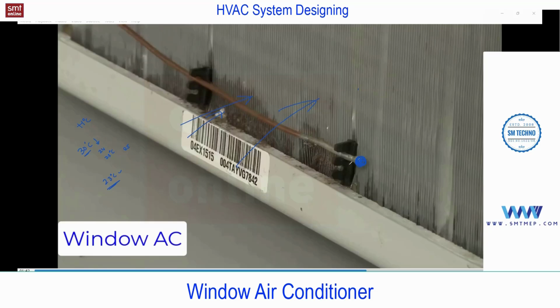And this can be asked in interview. Or in short, I can say return air temperature is responsible to control the compressor on and off for window, split or ductable split, etc. This is an important point.